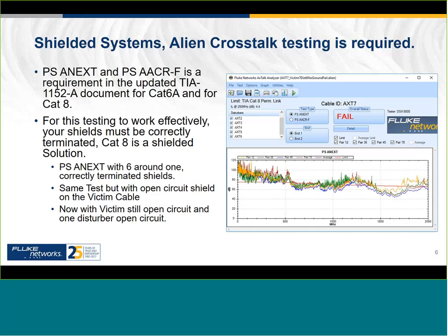So as you can see, shielding is highly important with these newer forms of cabling systems, especially as we move to high-speed data on category 8, which is capable of transmitting 25 gigabits or 40 gigabits per second. And this sort of then also shows the importance of those shields to keep noise out of those cables.